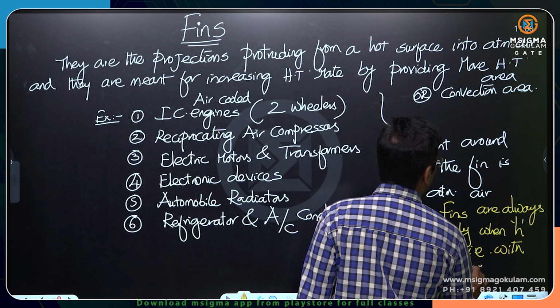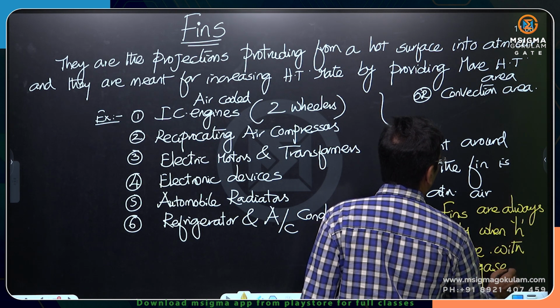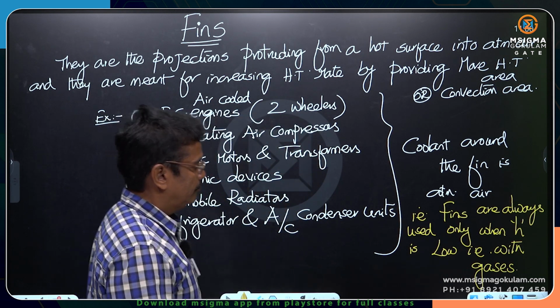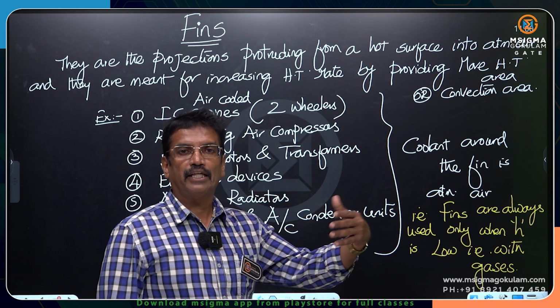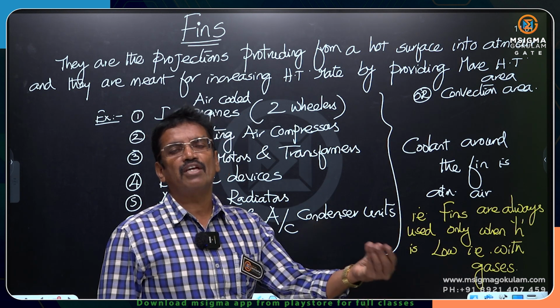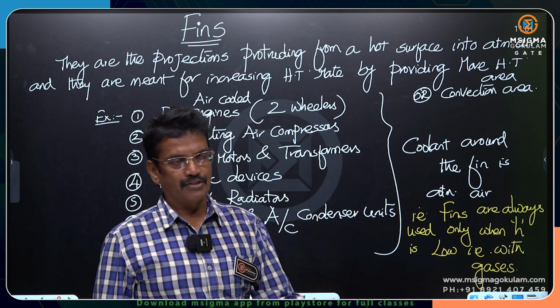Only with gases the h value is low. When h is high, that is with water, we don't need fins. We don't have to keep the fins. It is a mere waste of money keeping the fins.